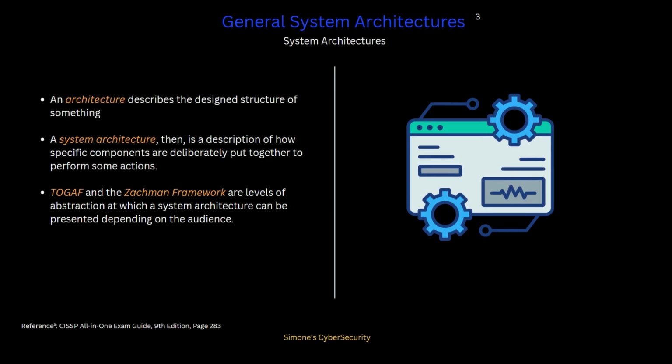So, by studying the architecture of the OT and ICS system, we will find more components like the data historian that we know are going to be dual homed, that are going to talk to both IT and OT, and that can become pivot points for attackers to move from IT towards OT. And that's why we know these are the components that we need to secure more. So that's why understanding system architecture becomes important in deciding the right security controls and right enforcement boundaries for the most exposed parts of the system.